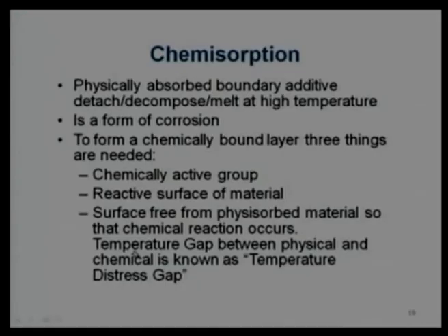And there is another guideline given over here. He said that try to use both processes, physical adsorption as well as chemical adsorption. Both are possible. If I choose a surface which is chemically as well as physically acting with the lubricant additives, then I can get good results. At low temperature, physical attachment; at high temperature, chemical attachment. The same lubricant additives can be used.